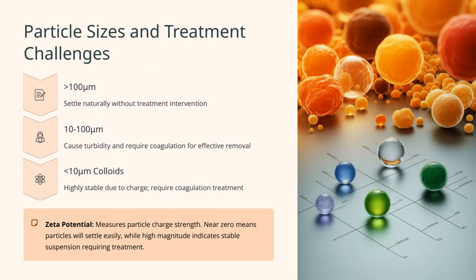Let's take a closer look at particle sizes and the challenges they present during treatment. Particles larger than 100 micrometers, for example, tend to settle naturally without much intervention, which makes them relatively easier to remove. However, when we move into the 10 to 100 micrometer range, things become a bit more complicated.